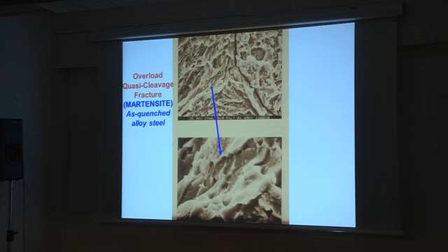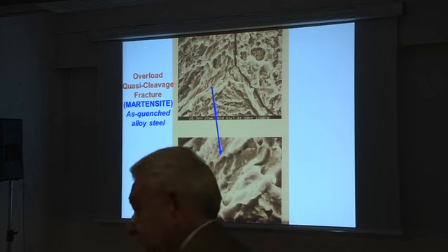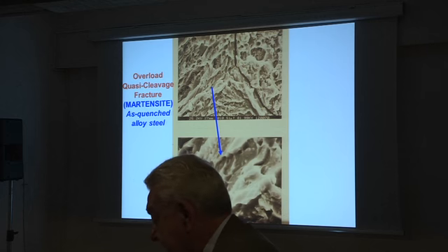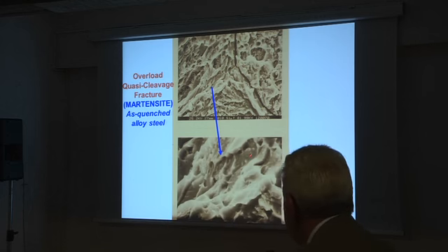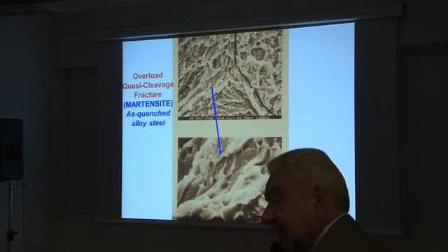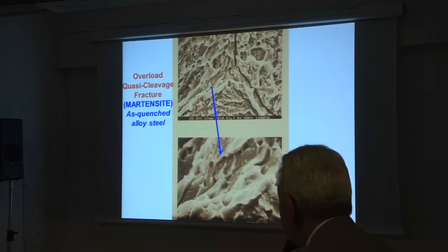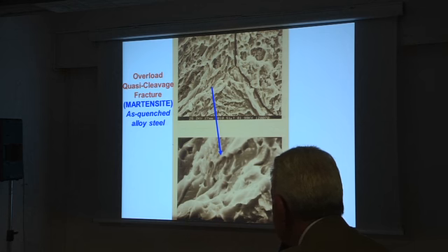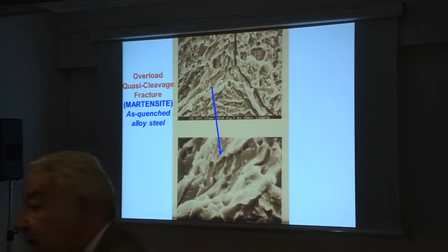When you have another type of monophasic steel, but with crystals much smaller, like in the case of martensite, the process is more complex. It is called quasi cleavage. Why is that so? You see, this is a cleavage facet. This is an enlargement of this position, but you see that there are some little holes. These little holes absorb energy.